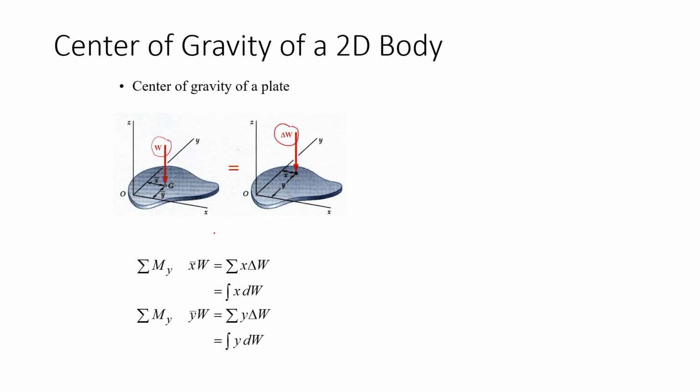So the concept in physics is more or less the same as Varignon's theorem. The total weight times the distance of your centroid, that's on the left side, is equal to the sum of the different parts of the weight. Meaning if we chop it up or divide it, it is just the summation of the different parts of the weight multiplied by their corresponding respective centroid distances.